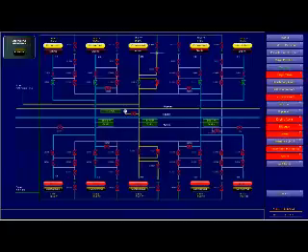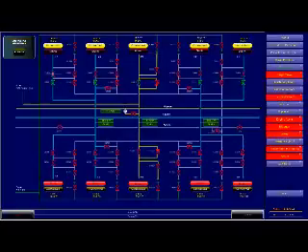No, manifold. Yeah, this is your manifold. No, that is right. Just open. No. There are two valves. This is the ESD valve. Open the ESD valve. Can you now see? The liquid is flowing out.